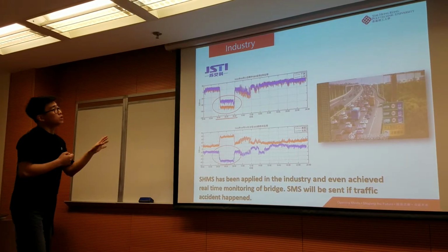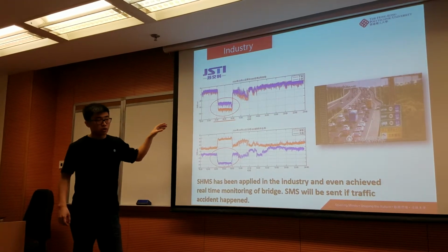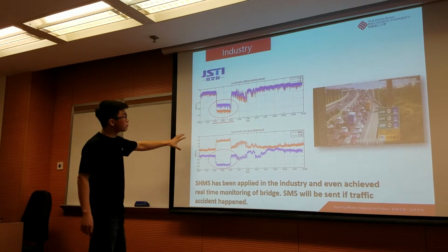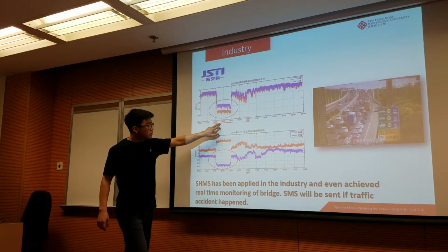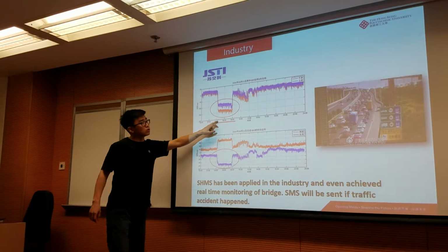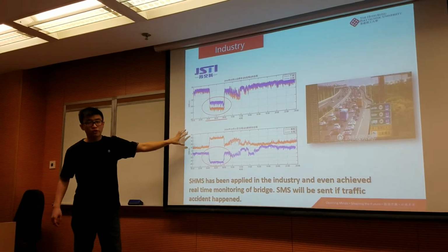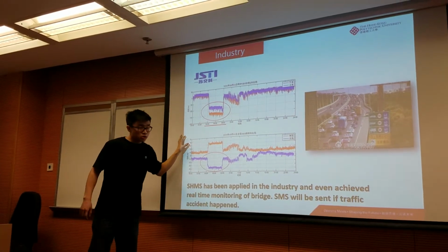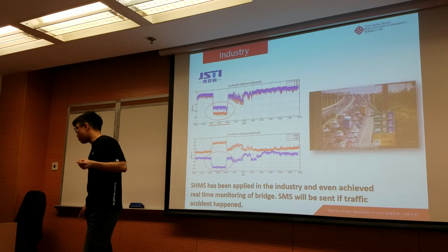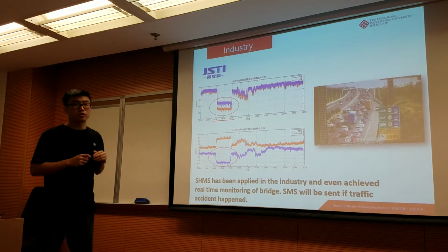And this is an industrial case in China. Here, we install wireless sensors on the bridge to monitor the deformation of our deck. And you can find that from 4 a.m. to 8 a.m., there is a sharp change in the deformation of our deck. This is caused by a very heavy traffic jam. So in this case, we can find that our structural health monitoring system powered by wireless sensors has already been applied in the industry and even achieved real-time monitoring.